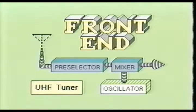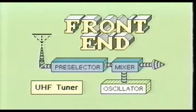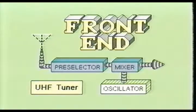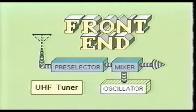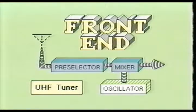The oscillator section in the UHF tuner will usually be a Colpitts or ultra-audion configuration. Due to the ultra-high frequencies, special transistors like the silicon epitaxial planar transistor are commonly used in this stage. The operating frequency of this oscillator stage is almost always higher than the RF signal it is being combined or mixed with.